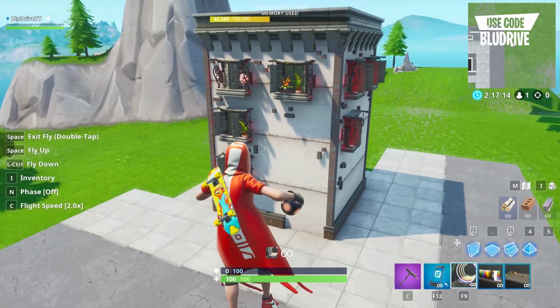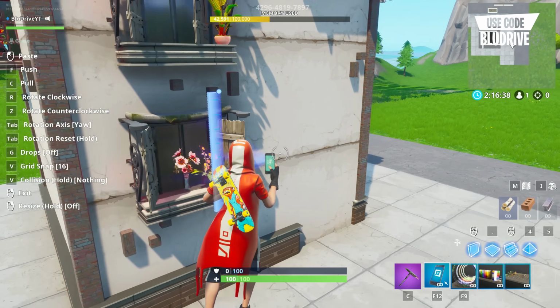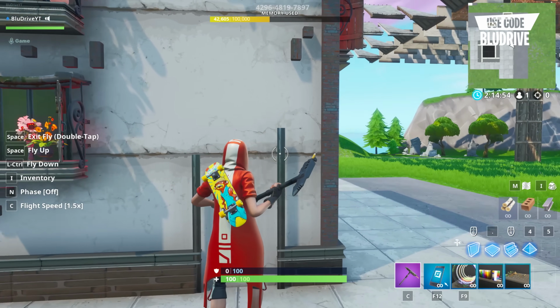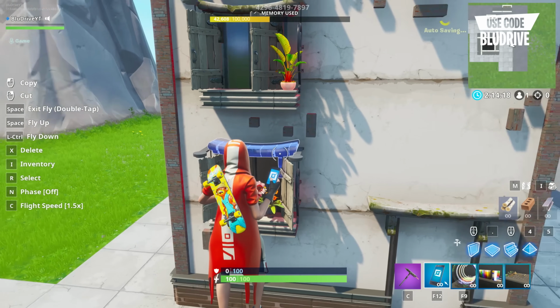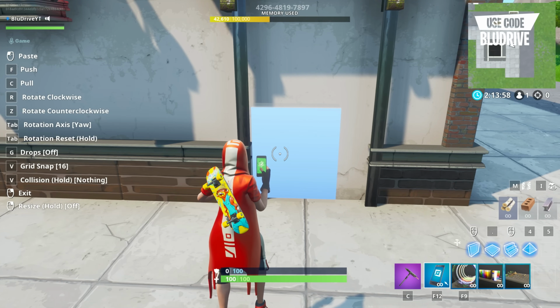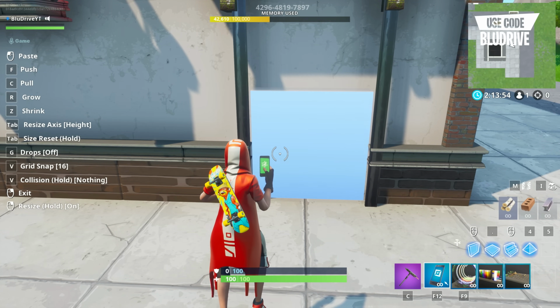Next we're going to create the main entrance to this cafe. We're going to start by copying this piece from the windows, and we're just going to change the height. We're going to make the top of these beams line up with this crack along the wall. We're then going to take this window piece and make it wider like this. This is going to be a glass door, so we're going to change the height of this to sort of fill out the rest of this door.